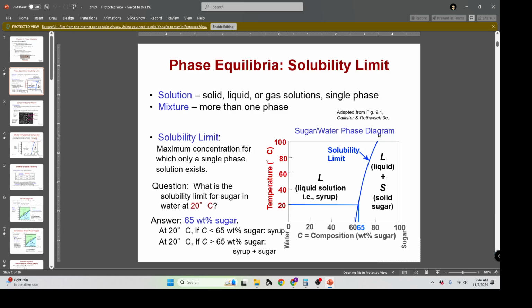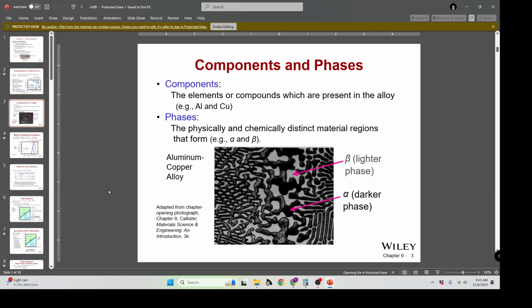There will be a line across which there is a limit of solubility, how much can be dissolved, and that's very, very important. So you'll have multiple phases, often in these crystals, in these metals, and we have a bunch of the key aspects of the behaviors of materials wrapped up in how these phases are coupled together.